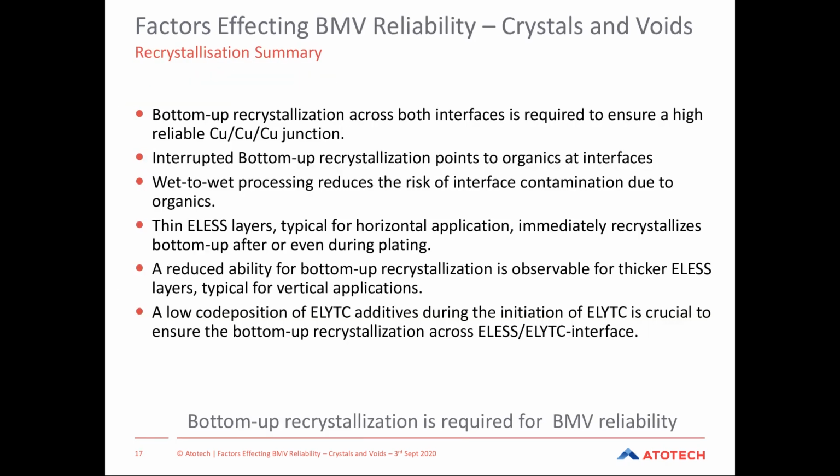The next one should just be a summary. Yeah. So what we're saying is, ideally, you want a fully bottom-up recrystallized microvia structure. That single crystal structure across the target pad and into the plated layer itself. In order for that to occur, it's suggesting that the process is well controlled and that all the interfaces are clean, because there's a very low level of organics within the plated structure itself.